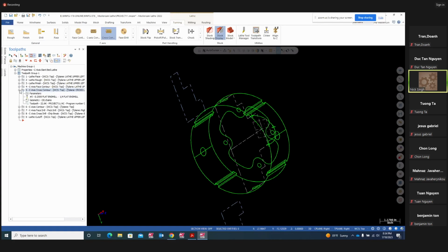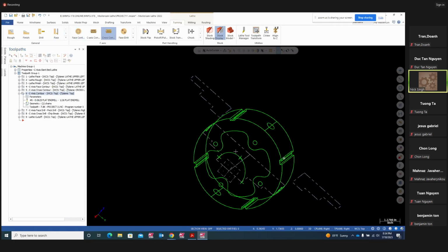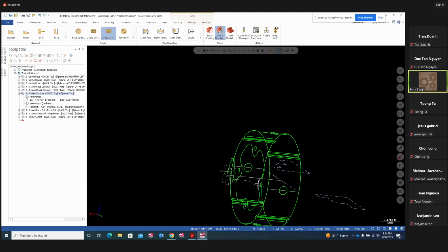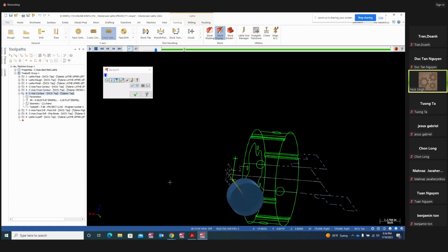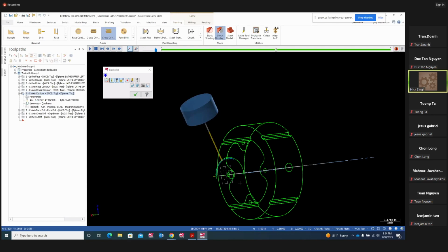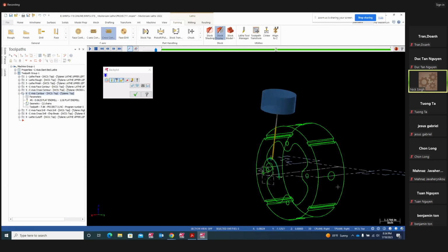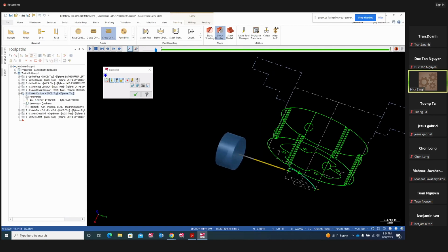After C-axis cross contour with a 1/4 inch end mill, we have C-axis contour, which is going to be your 1/16th end mill. That is going to cut this arc right there, this guy right there. I'll show you how we're going to draw that. Give me 1 second. So that is going to be toolpath C-axis contour. It's going to cut on your C-axis, on that arc. There you go. It's right there. And same thing on this one here. We are cutting right on the arc.